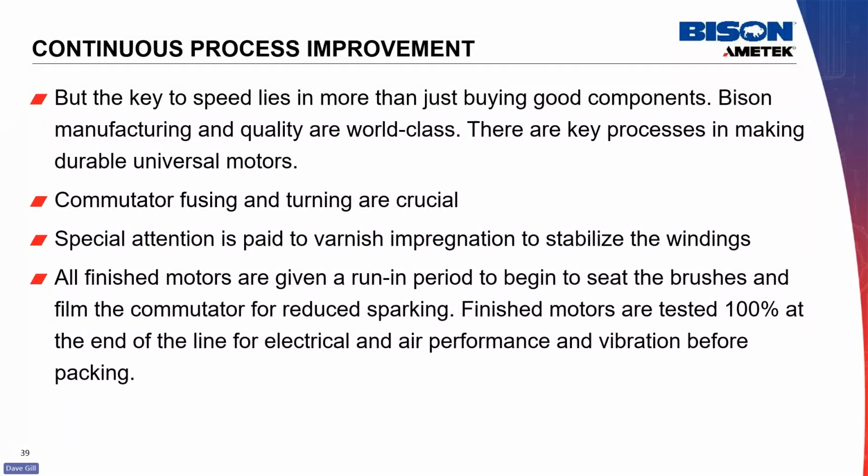And all finished motors are given a run-in period to begin to seat the brushes and to film the commutator for reduced sparking. Finished motors are tested 100% at the end of the line for electrical and air performance and vibration before packing.